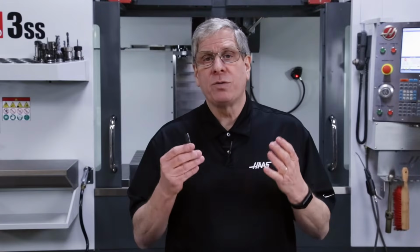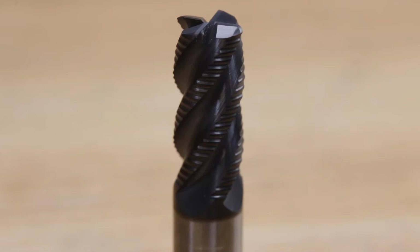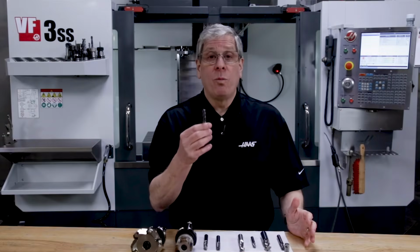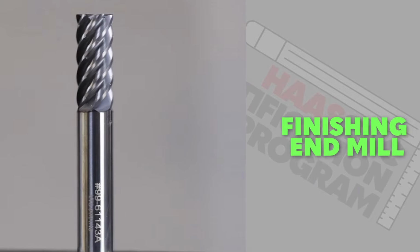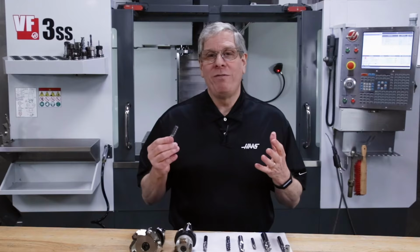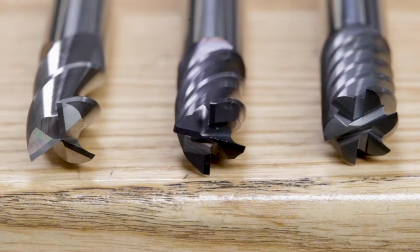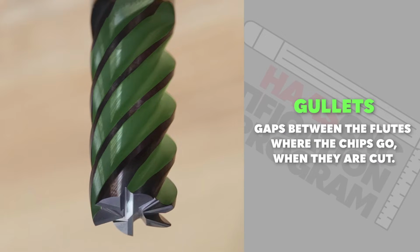Anytime you see slots or grooves in the cutting edges of a cutter, it's because that cutter is designed primarily for roughing. So, if we have roughing end mills, are there end mills designed solely for finishing? Silly question, of course there are. Usually end mills with more than 5 flutes, or cutting edges, are designed for finishing. The more flutes there are on a milling cutter, the smaller the gap between them. These gaps, known as gullets, are where the chips go when they're cut.